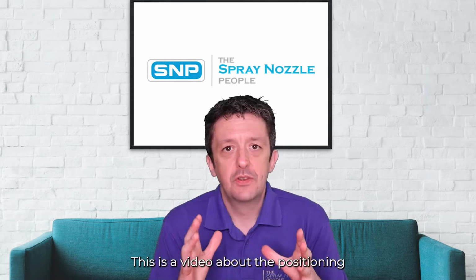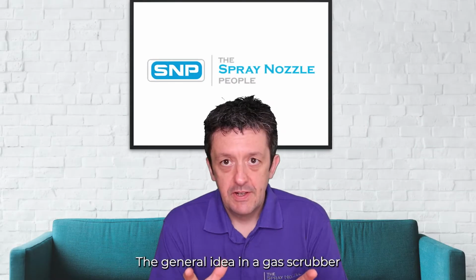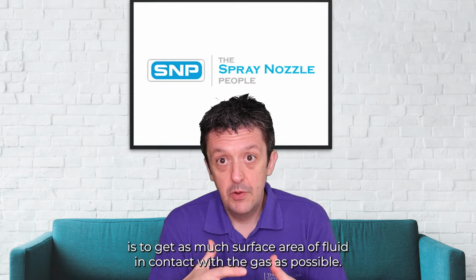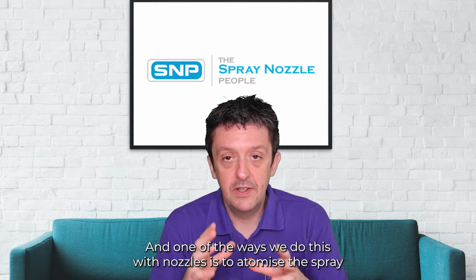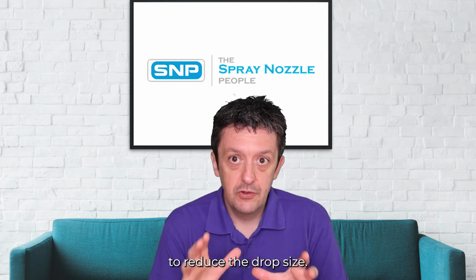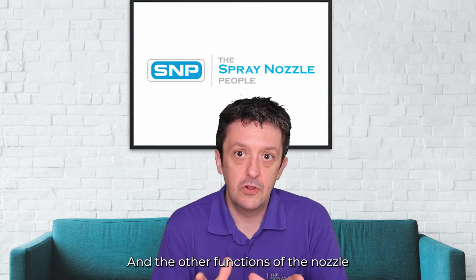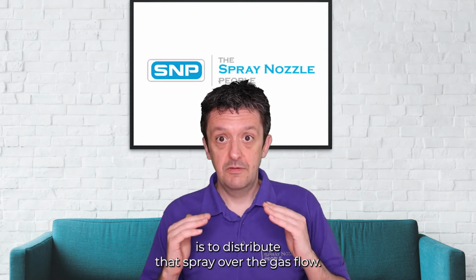This is a video about the positioning of spray nozzles in gas scrubbing applications for optimal results. Now, the general idea in a gas scrubber is to get as much surface area of fluid in contact with the gas as possible. One of the ways we do this with nozzles is to atomize the spray to reduce the drop size. This increases the surface area of the spray. The other function of the nozzle is to distribute that spray over the gas flow.